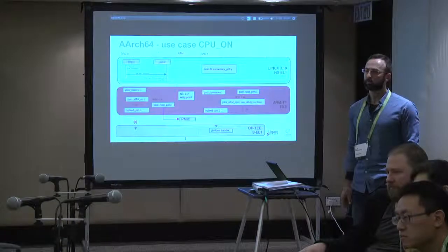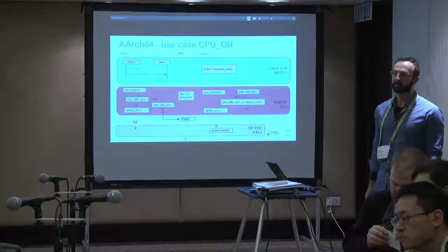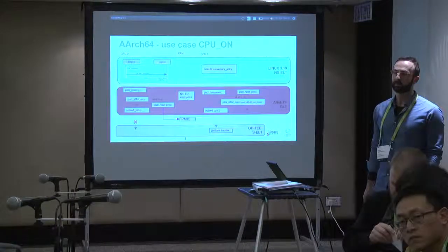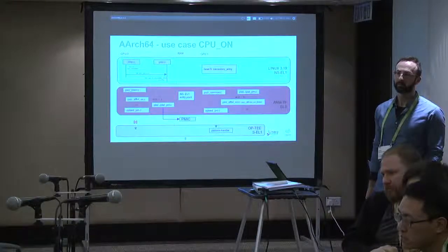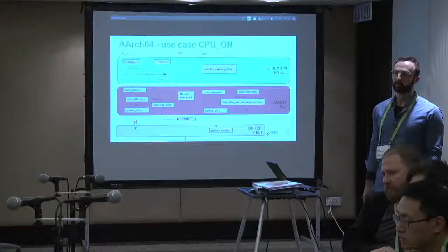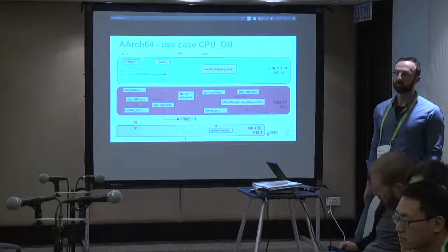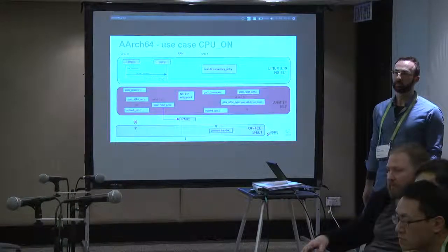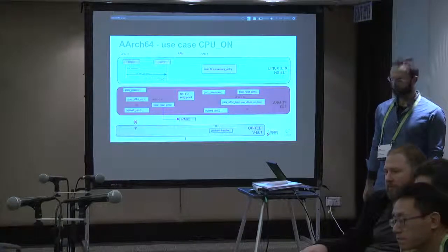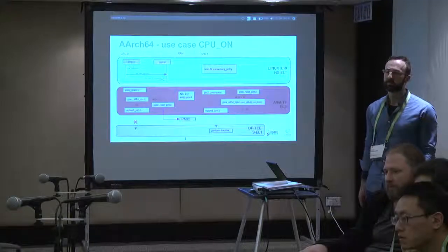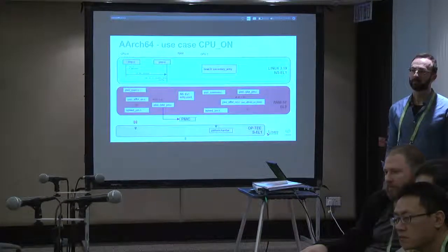It could be done from the Linux side or integrated in the SCP or in power management hardware. Actually here, if we are going to power off CPUs, let's say we have 8 clusters, each has 4 CPU cores. Now working only 2 of them. So it's difficult to apply a retention voltage on the clusters which are not in use right now.